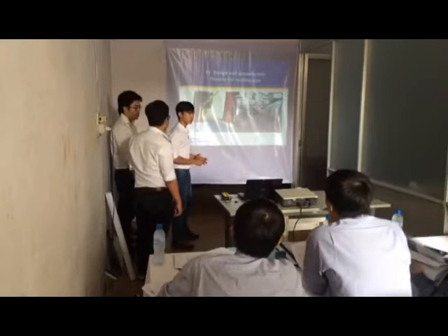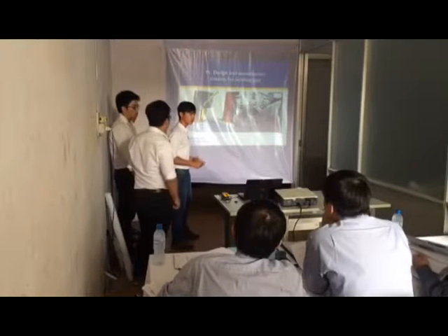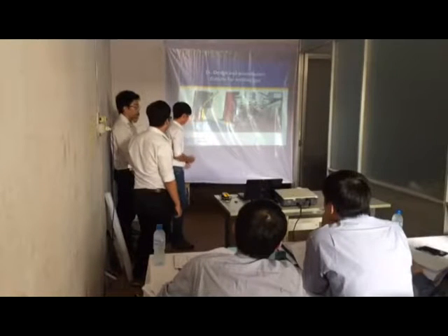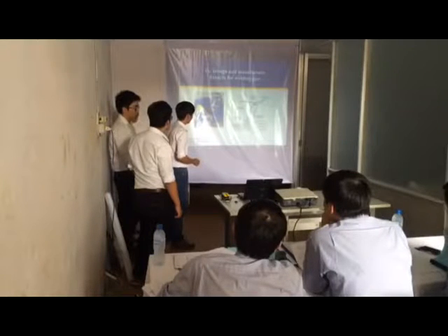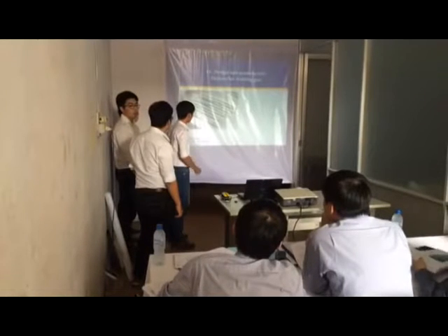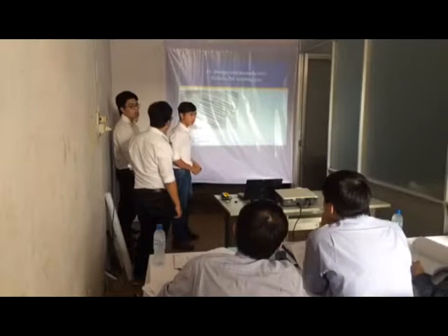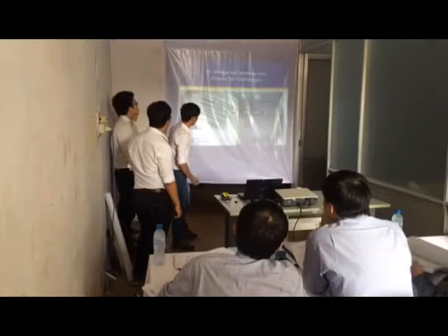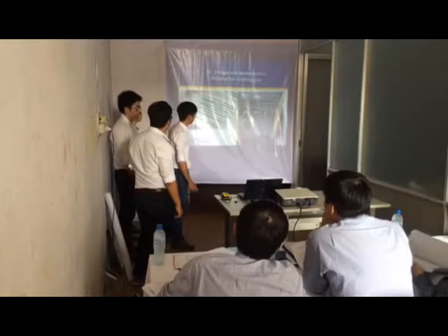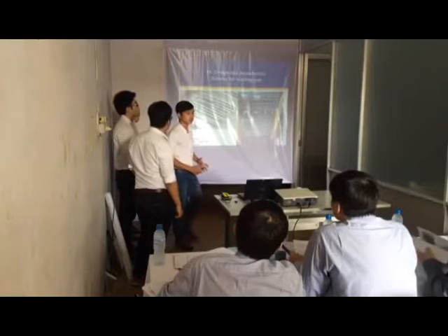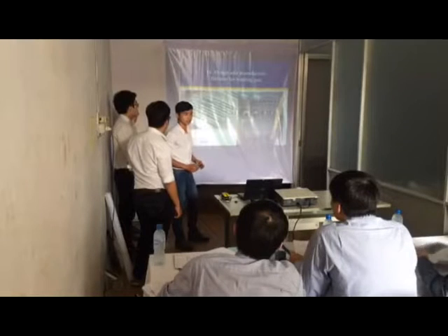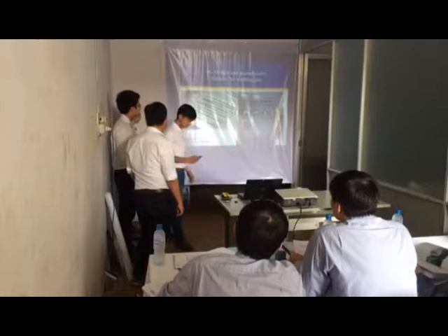So we set it up at a special angle, like this. To have a good weld line, I think the manufacturer has to consider the voltage, the current, the speed, and the distance between the nozzle and the workpiece.